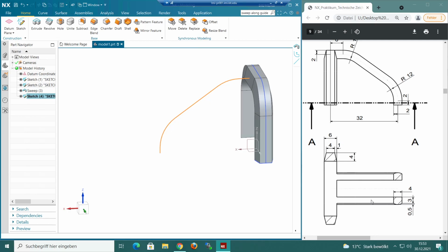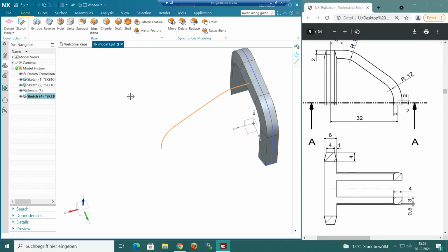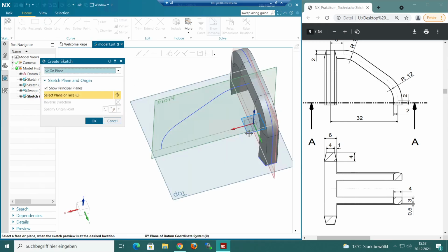You have to imagine it like a guideline which will be used, but on your section curve. So the extrusion or projection, or however you would call it, will always start from the section curve and then follow the direction of this curve from there. So it doesn't matter where the curve is, it's just taking its direction, not its position, okay? I hope that's clear, because I think it's always nice to also understand how the functions are working.